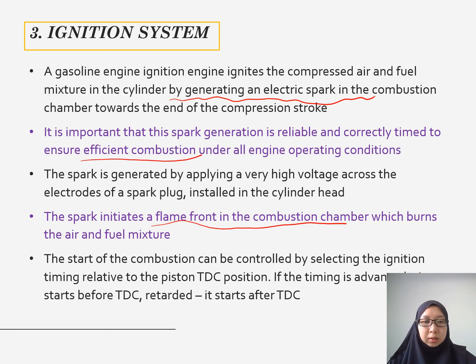The start of combustion can be controlled by selecting the ignition timing relative to the position of top dead center. If the timing starts before TDC, we call it advanced, and we call it retarded if we start after top dead center.